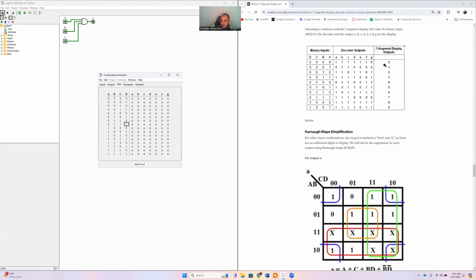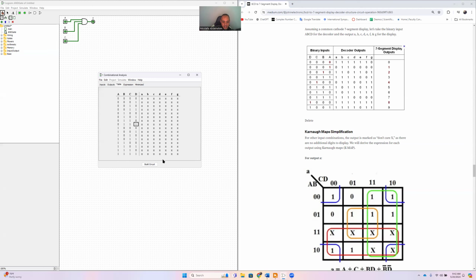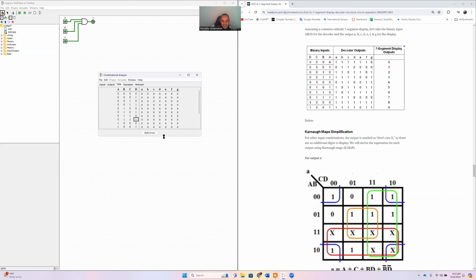This is a complete one. The one on the right here is just truncated, right? So for that truth table here, we're gonna use only the first 10 cases from 0 to 9. 0 to 9 is 10, and all the remaining cases will be only don't cares. Okay, so I'm gonna reduce the size until just the cases that we want and enter them here.